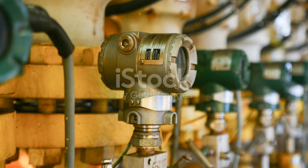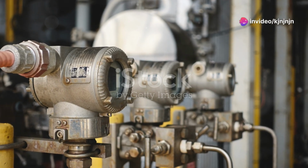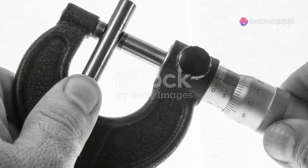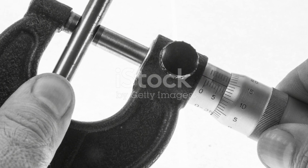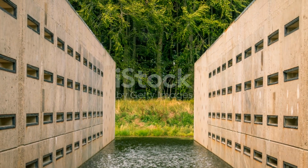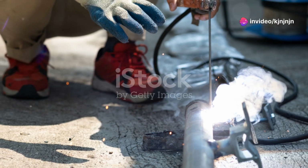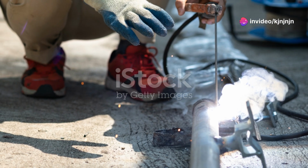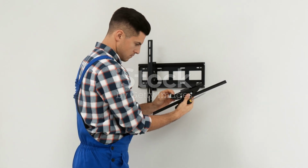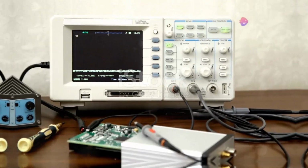Mounting methods for strain gauges vary depending on the application and the type of material being tested. Surface mounting is the most common method, where the gauge is simply bonded to the surface of the material. Embedded strain gauges are placed within the material itself, providing measurements from within the structure. Weldable strain gauges are designed for high-temperature applications and are attached by welding. Proper mounting technique is essential for ensuring accurate and reliable strain measurements.